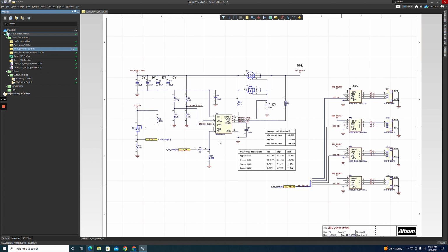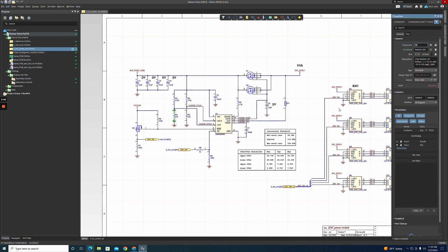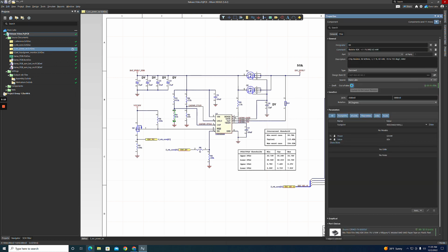And we'll also check to see where the CPNs that are generated by Duro show up in Altium. So if you double click on a component, we need to click the refresh. Now that we've refreshed, if we click Show More under Parameters, we'll see that this part now has a property of PLM part number. This corresponds to the CPN that is generated by Duro.